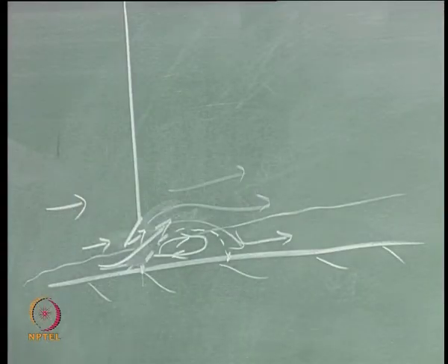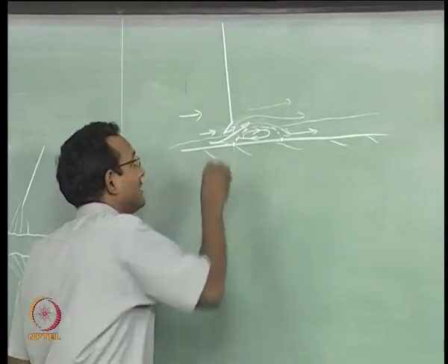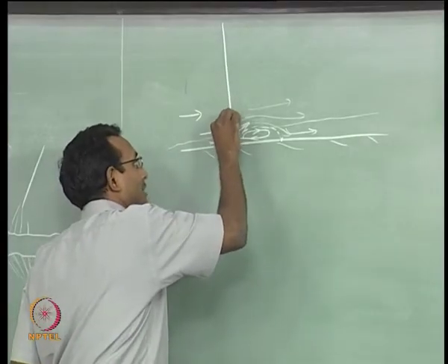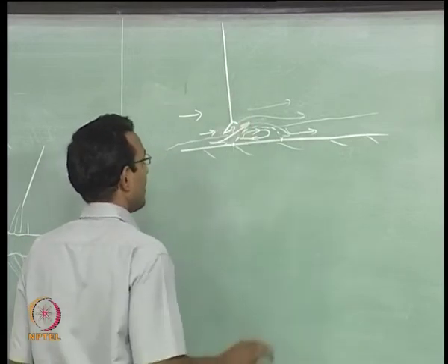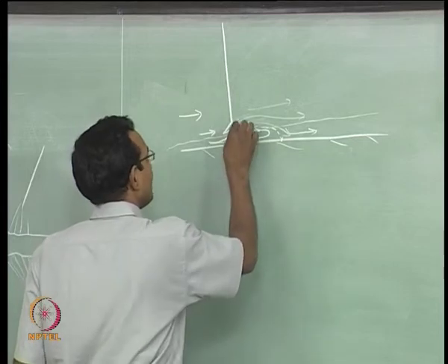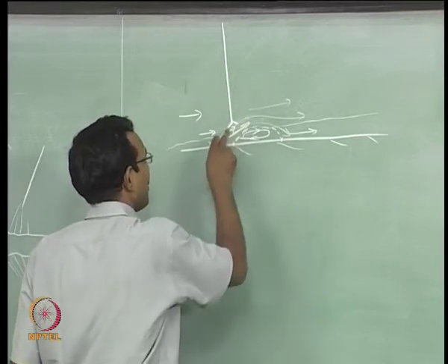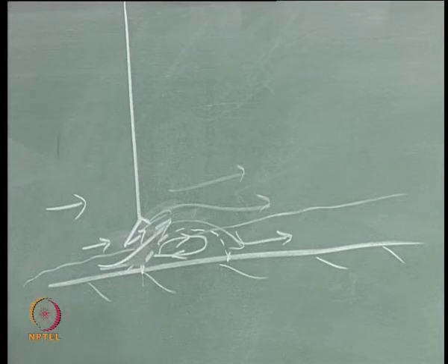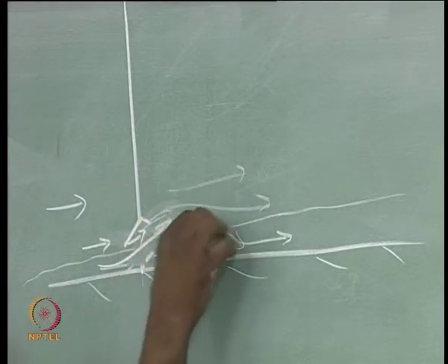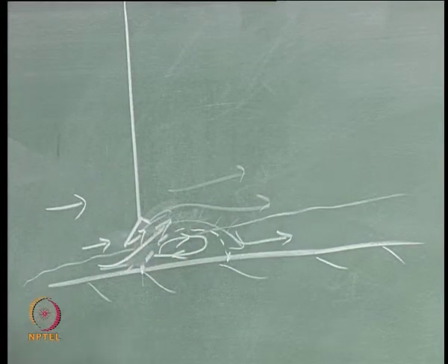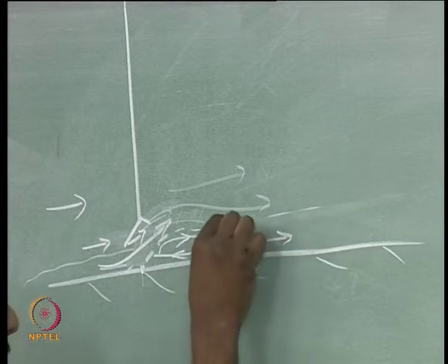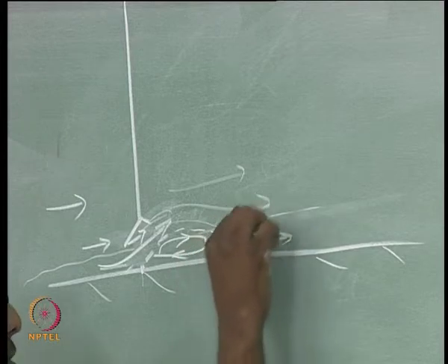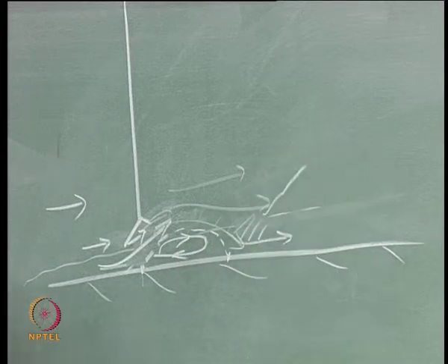Okay. That is too much of aerodynamics probably for you right now. But what happens at this corner is there will be a small shocklet here. We will not worry about why it is formed right now. Okay. And after that the flow field is again supersonic flow or subsonic flow depending on the conditions here. If it is supersonic flow, then there will be expansions. If there is expansion and then again the flow has to turn back, there will be compression waves which will again form a shock.